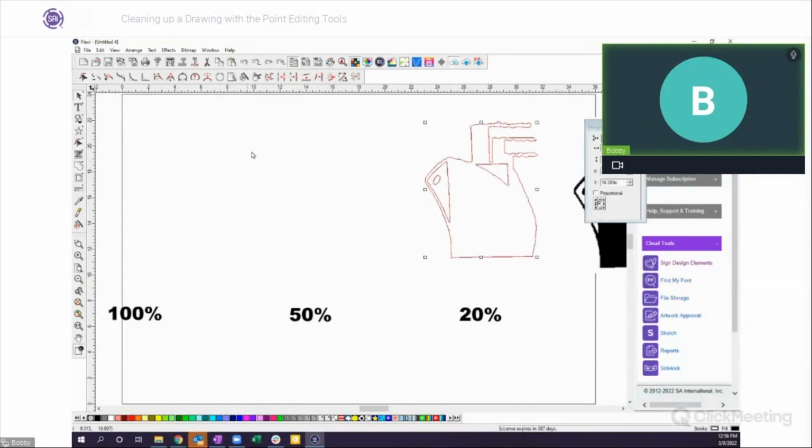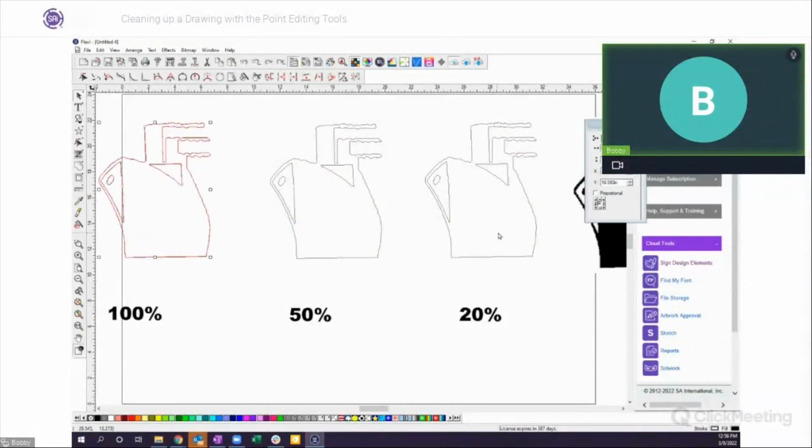So what I want to do here is I'm going to select this right here. I'm going to hold my control key down, and I'm going to make a couple of copies here so we can kind of see the difference in the different selections that we have. All right. So let's select this one first. Get the whole thing here. And I'm going to go to reduce points. So there it's showing my points. Let's make my tolerance 20 here and click the check mark. And you'll see it got rid of a couple of points, but not very many.